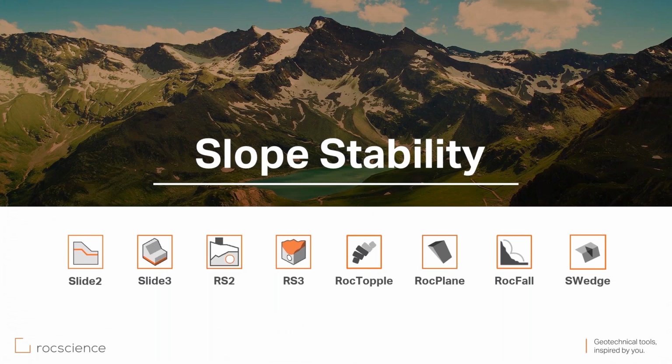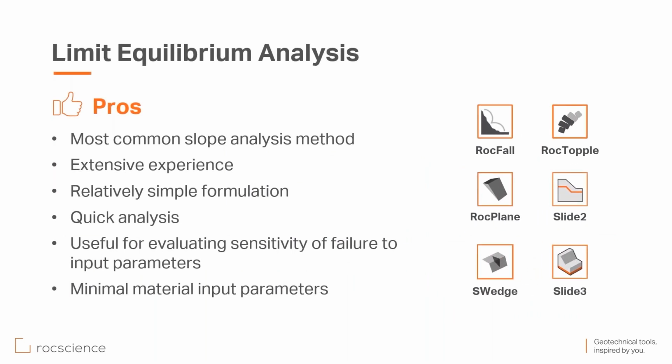When it comes to slope stability, Rocscience has a versatile arsenal of tools that, depending on the problem you're dealing with, we can apply the appropriate tool to that slope stability problem. The list can be categorized into two sets of algorithms, except for RocFall, which is a statistical analysis of pieces of rock falling from a slope. The rest of them, RocTopple, RocPlane, SWedge, Slide2, Slide3, mainly use limit equilibrium analysis.